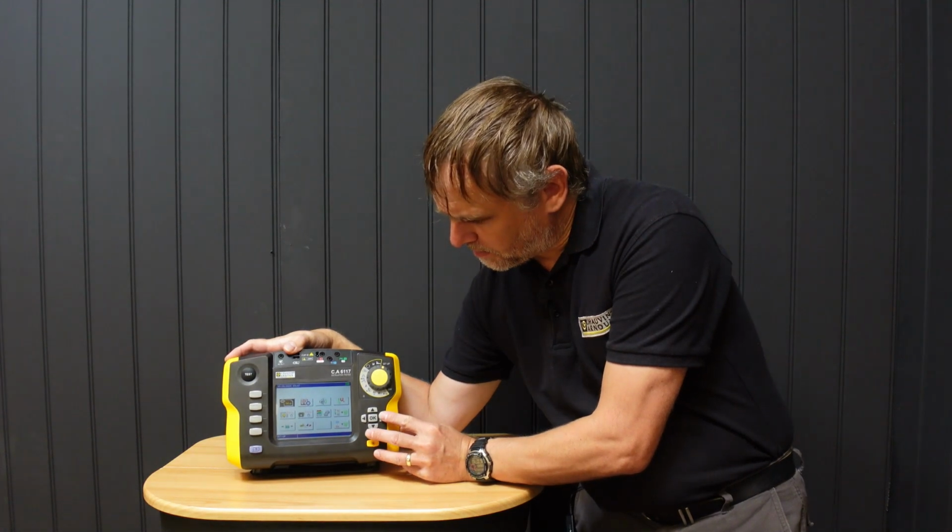One thing to note with the audio feature is that for it to work, the audio must be set as on in the global setup menu, as that overrides the individual test settings. If the global option is set to mute, then the instrument will not make any sound on most tests, although the display will still visually show either a tick or a red bell icon for any result below or above the programmed threshold.